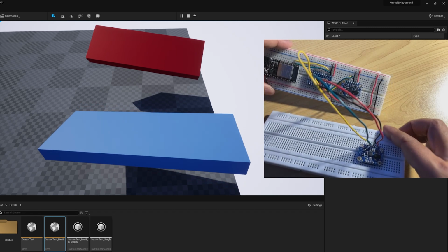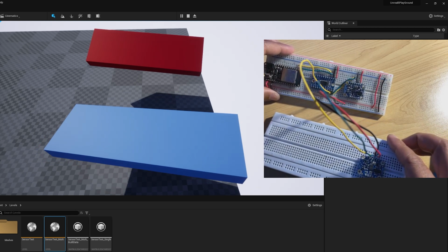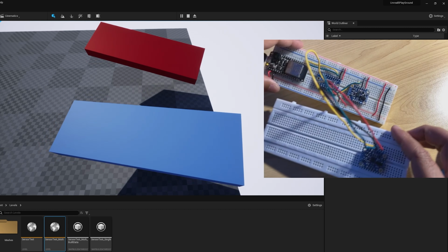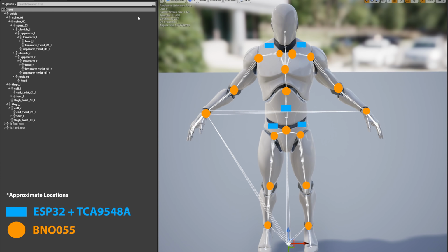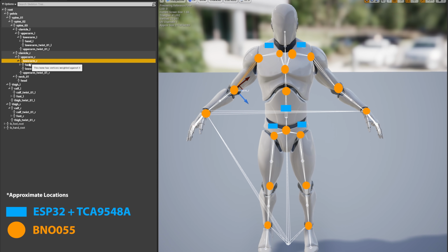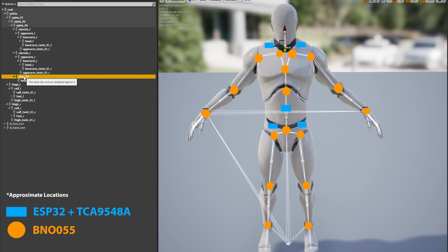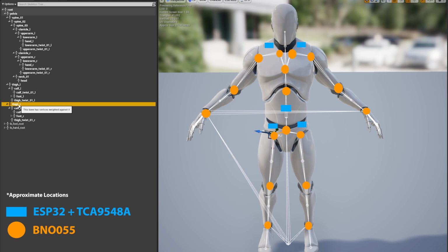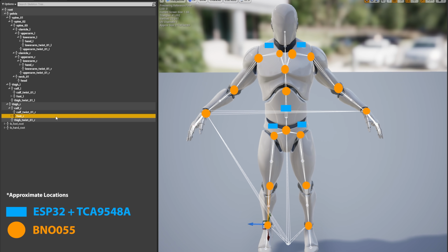And here you can see two BNO055 are connected to one ESP and sending a data pack with both the sensors together. For the final presentation, when I will be mapping the sensors with the human rigid body, I will be needing 17 BNO055 sensors. And if I could use 3 or 4 ESP32, then all the 17 can be clubbed inside 3 or 4 ESP32 devices. I will definitely look into the final prototype very soon.